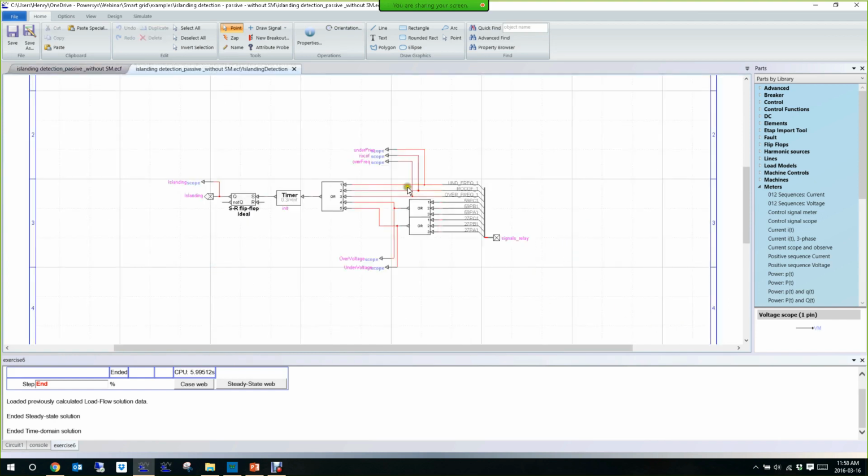And you can see now I have a small strategy. Anytime I have one of these signals, I detect islanding. So here it's your choice. You can add some delay, because you know here it's easy. I do a scenario, I will see a frequency change, and I detect islanding. However, you have other types of study to do. You have, for example, to apply a fault and remove the fault and make sure that there is no islanding detected for that. So you have to simulate a lot of different events to see if you detect islanding only in case of islanding and not in case of fault or load shedding or stuff like that.